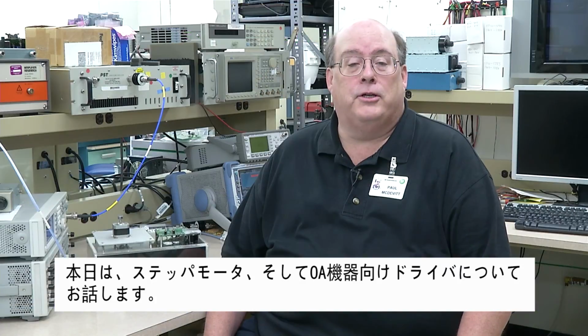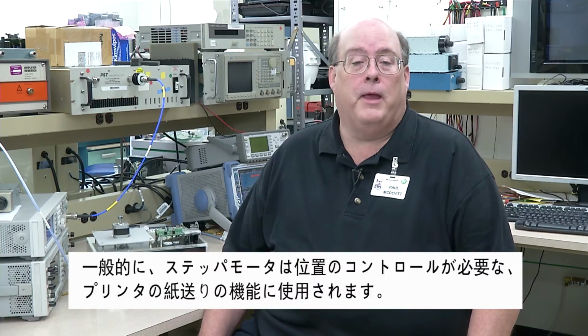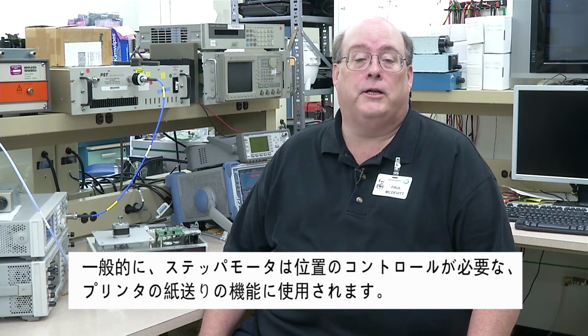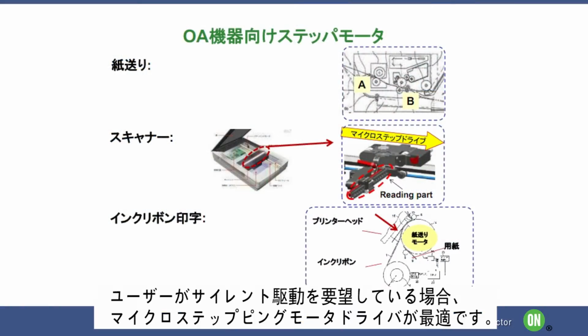In today's discussion, we are going to focus on stepper motors and drivers for office automation applications, including end products like printers and scanners. Typically, a stepper motor would be used in a printer for paper feed because this function requires positioning control. Stepper motor paper moves from point A to point B accurately, as shown in the right-hand side figure. If a silent drive is the end user's priority, a microstepping motor drive is recommended.